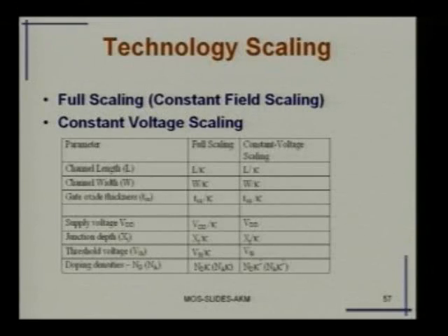Professor Chakravarti told me to quickly go through the scaling. The expressions we have discussed are general, in terms of L, W and area. Now, what we are doing is trying to scale. Today we had a 1 micron technology, then we went down to 0.45, then 0.18, then again below that. So, essentially we are scaling the dimensions of the transistors. Now, as I decrease the dimensions, what are the effects on the major characteristics of this kind of inverters?